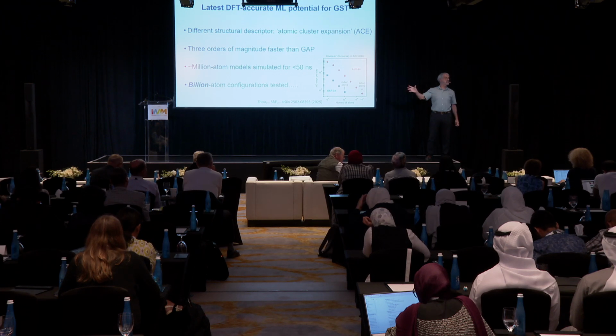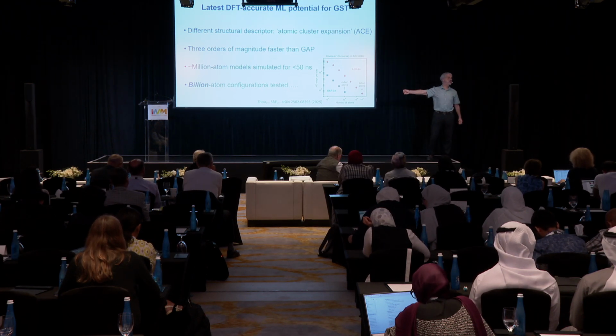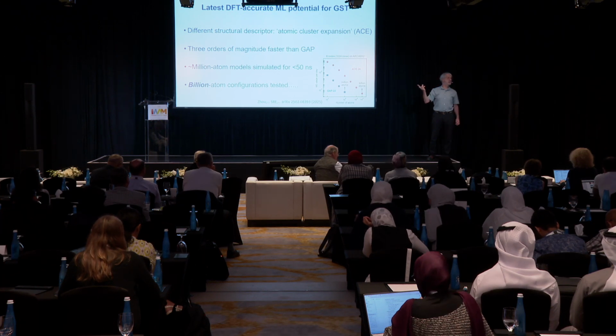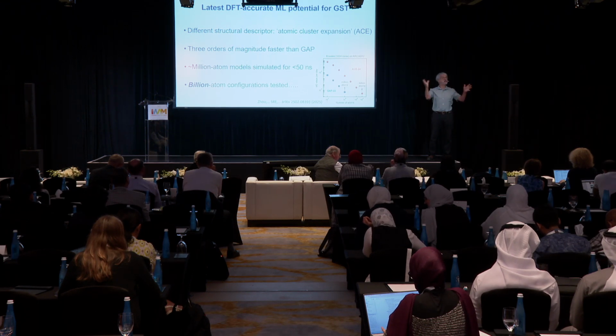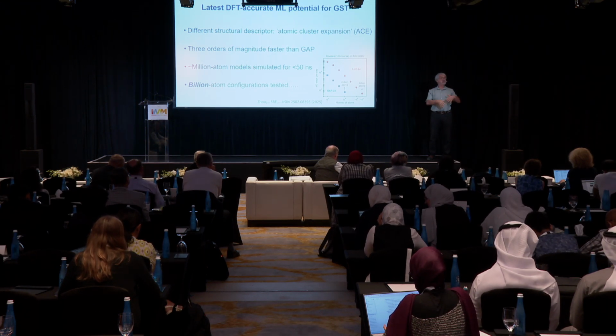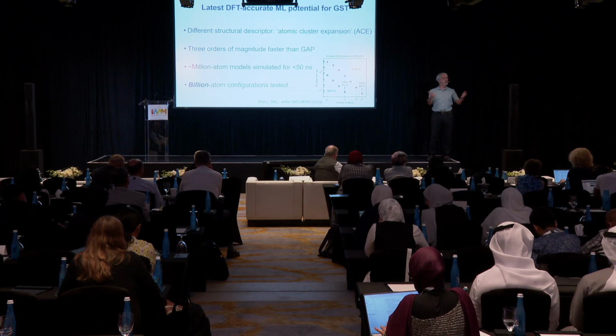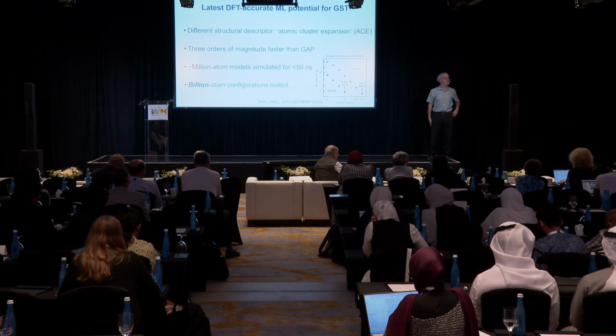So this material is quite fast. 5 nanoseconds to crystallize is pretty fast, and it's certainly fast enough for DRAM replacement. So we've got a non-volatile answer for DRAM. We're talking about sustainability: it means you don't have to boot up your computer. It's always on, basically.